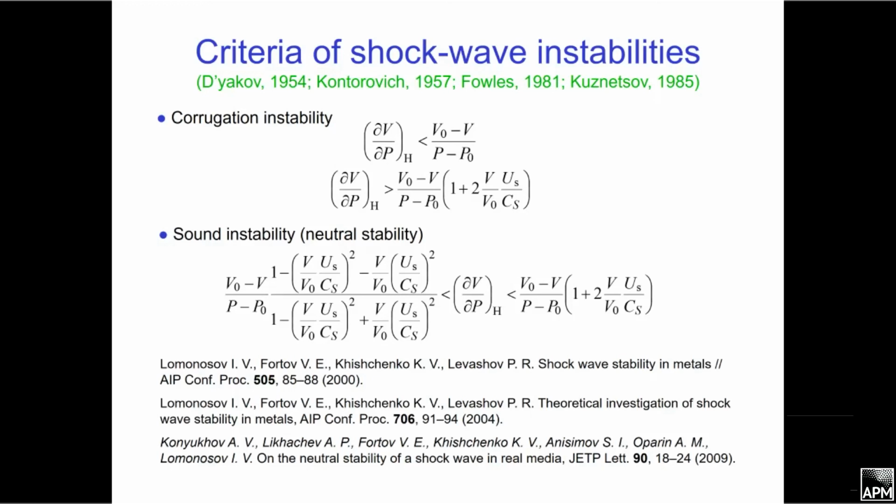Here you can see conditions of corrugation instability and also sound instability. Sound instability means that the shock wave is stable, but it is a source of sound waves, which can decrease the energy of shock compressed material.